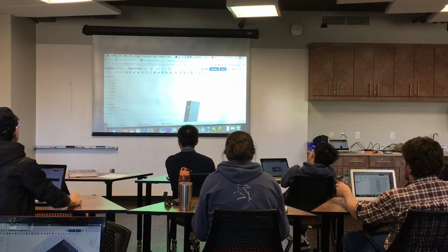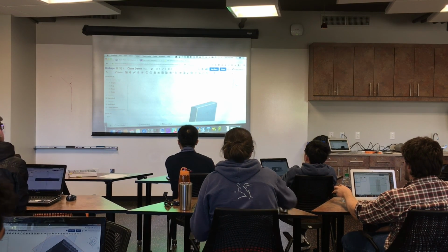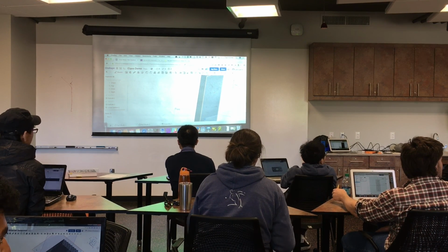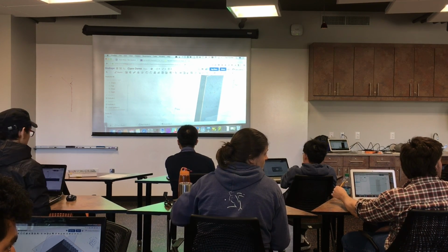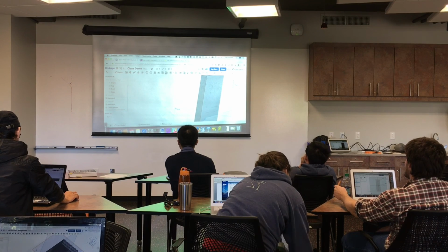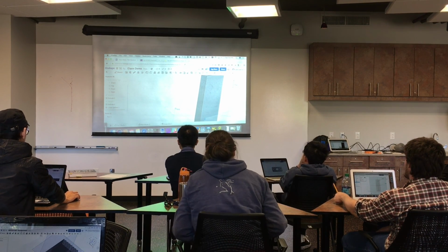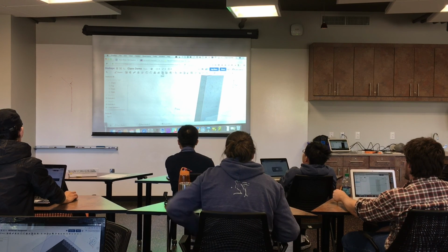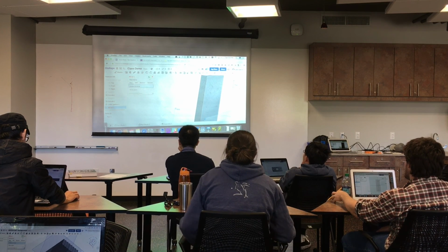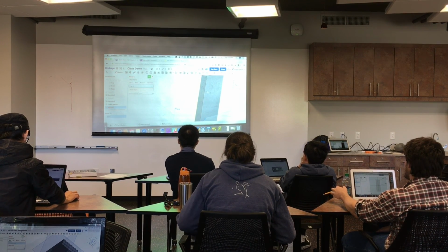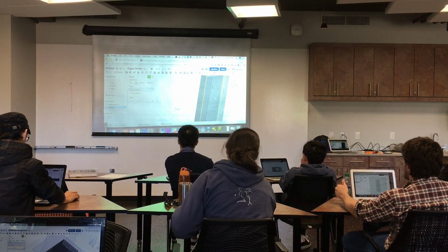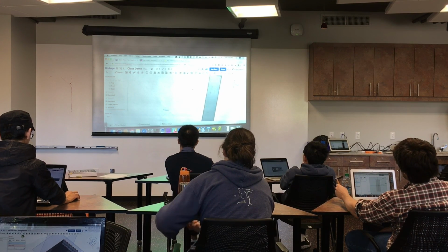Awesome. Now, the reason I only designed this with teeth on one side, though I want it to look, let's say, like this with teeth on both sides, is because I can leverage everything I just did. Somewhere up here there is a mirror command. There it is. I'm going to select mirror. I want to mirror a part. I can just click it. And the mirror plane, I want to mirror it across this plane. And I hit check.